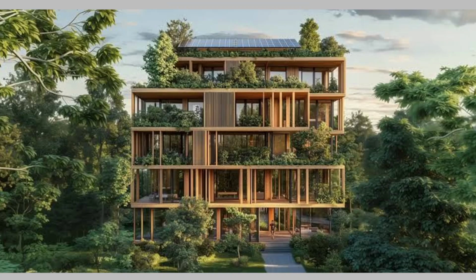Environmental and performance benefits. Carbon storage. 1 cubic meter of CLT stores roughly 800 to 900 kilograms of CO2. A mid-rise building can store thousands of tons. Embodied carbon reduction. Switching from concrete to CLT can reduce embodied carbon by 20 to 50% depending on the project.